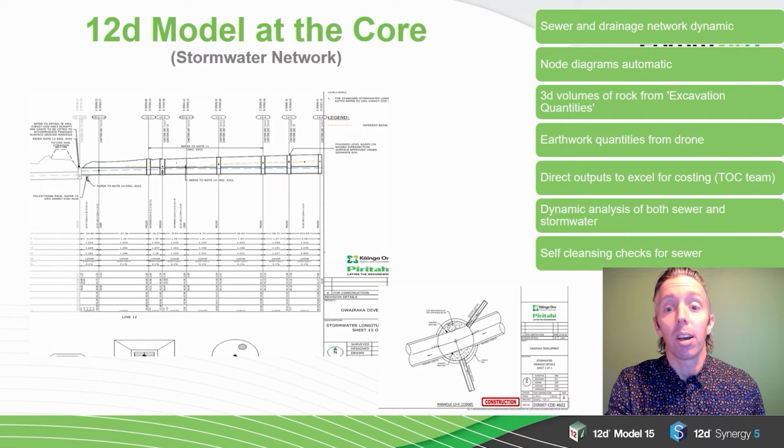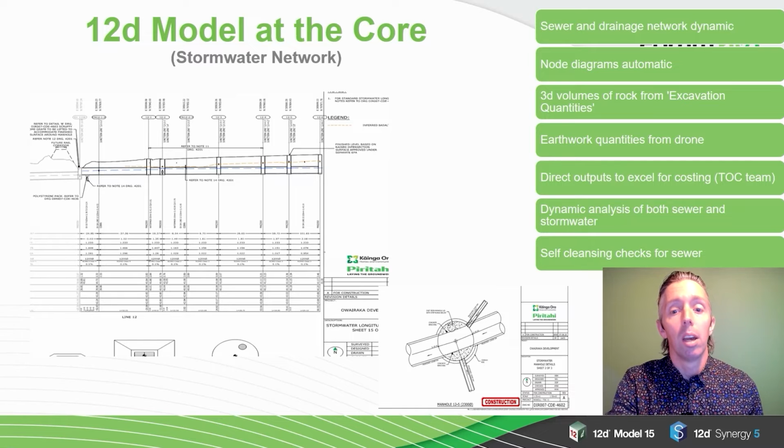We use the node diagrams in 12D regularly to export the manhole blow-up detail plans. These are an excellent feature and take away a lot of extra manual drafting that would normally be required. I will show you a quick clip on the next slide as I talk.